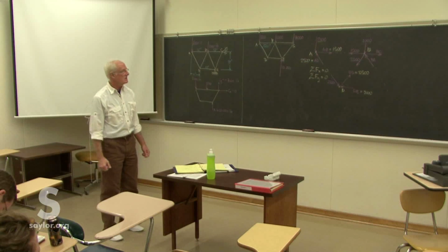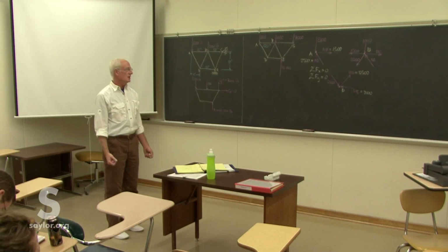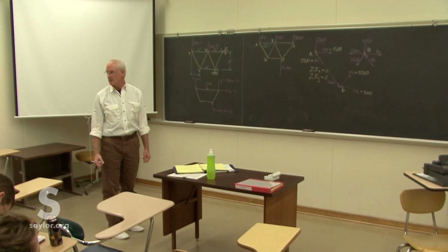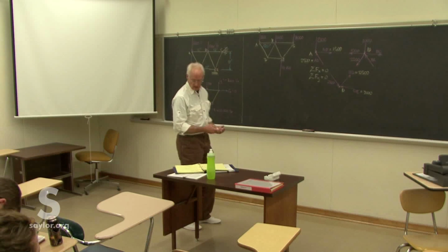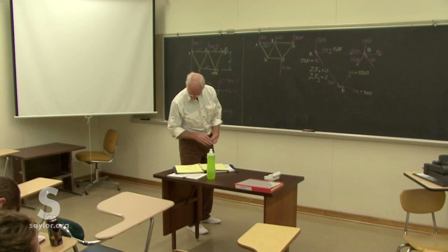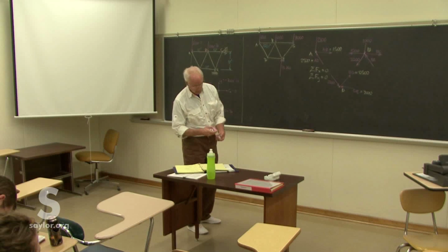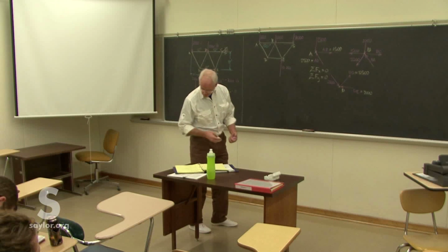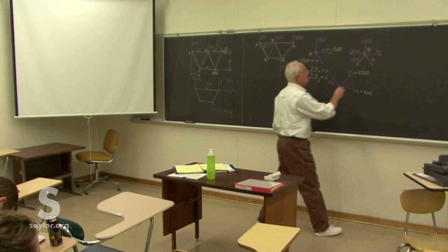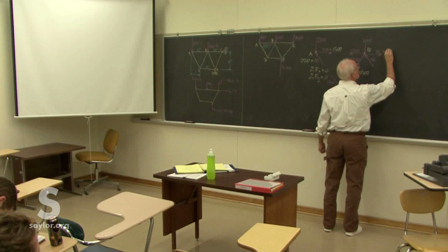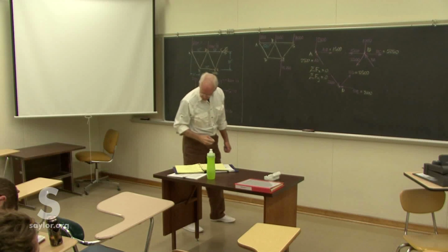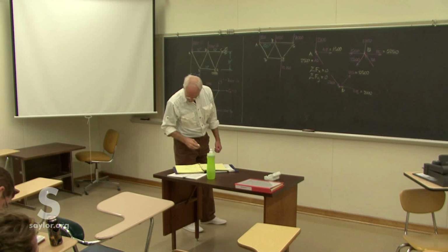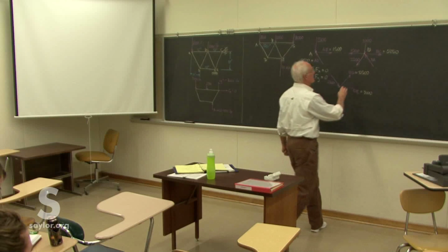There's two unknowns, two equations, a little more complex just because it's got a bunch of extra numbers in it, but still two unknowns, two equations. Sum the forces in the two component directions. All right, when you do that, turns out that this is 5250. Again, remember all is in pounds. And this is 3750.